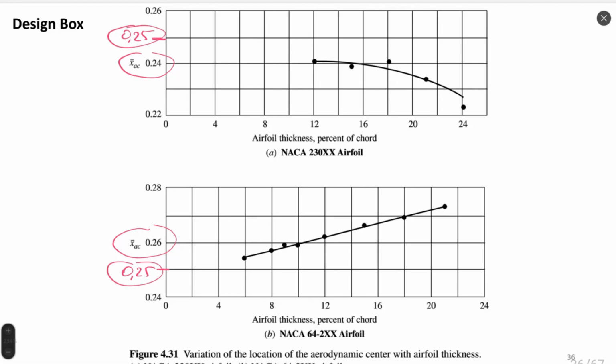We must remember this when we calculate any airfoil, and this was one of the questions I asked when I evaluated work one: why in many cases was the position of center of pressure, which is close to aerodynamic center, very different from 25%? In some cases it was even negative, meaning that the center of pressure is outside of the body.